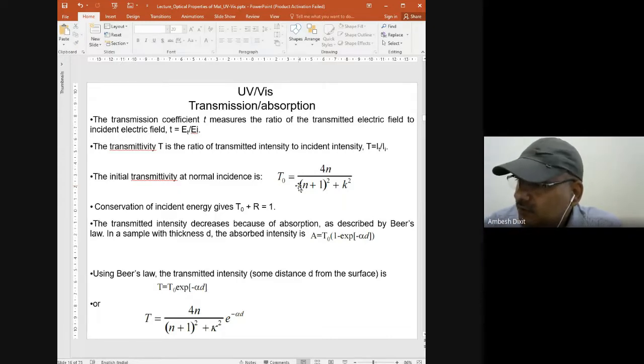So absorptivity is an integrated number over the entire wavelength range. Absorptance is a number that reflects the spectrum, how it is changing with each wavelength. So I can use absorptance to compute the absorptivity. Absorptivity is one number, an average number normalized with respect to the black body radiation. Okay. Right.